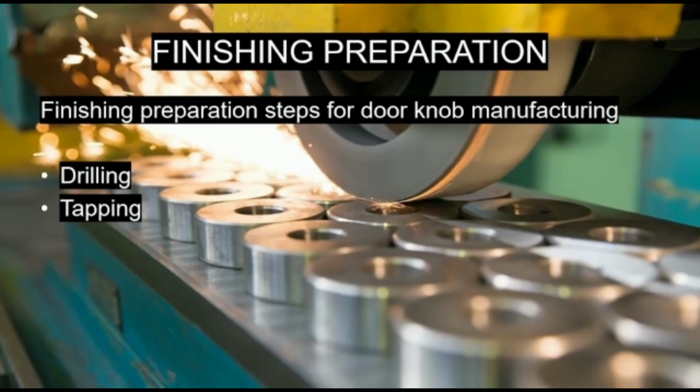For finishing and surface preparation, after the doorknob goes through the forging process, it goes through a series of finishing steps. First is drilling, which is pretty self-explanatory, a process that uses drill bits to cut or enlarge holes. And the second is tapping, a process of cutting threads using a tap.